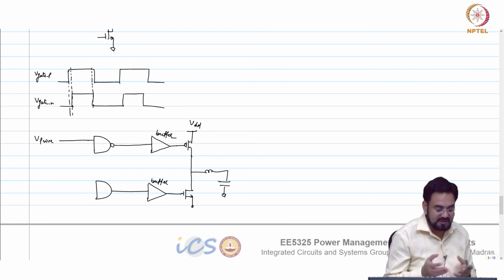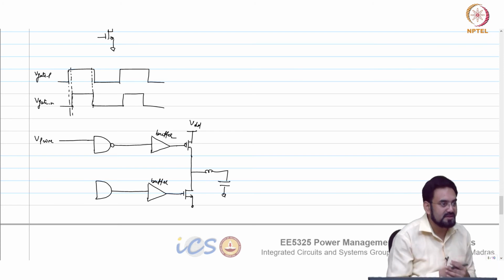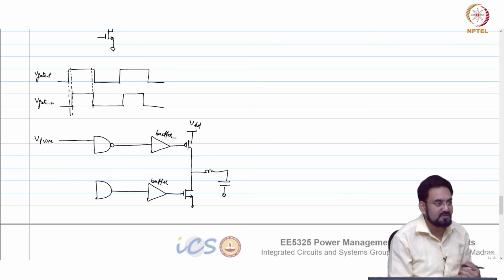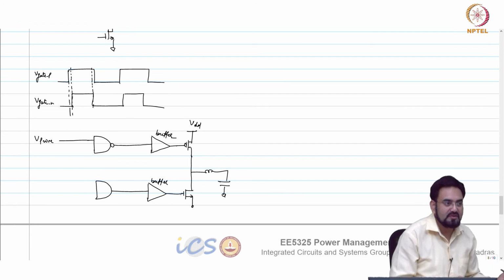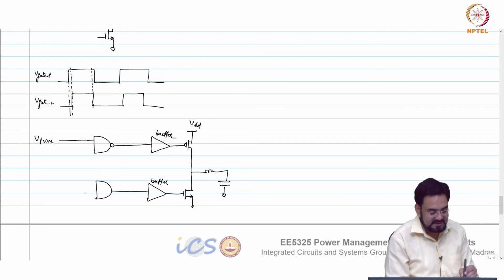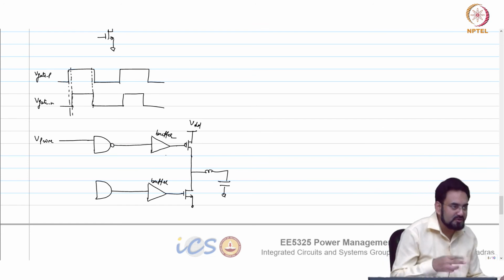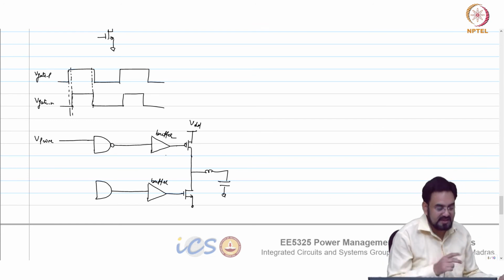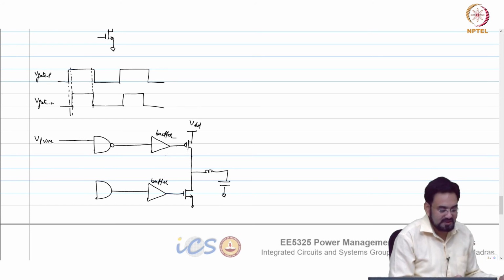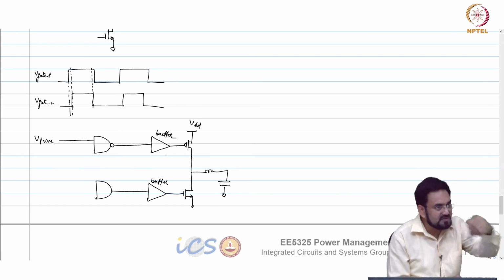You can say, okay, this can be done by using an OR gate or NOR gate, okay. NOR gate, if you make one input 1, it will go 0, but then in the logic, when you do the feedback, that may go wrong. But in this case, when the other input is, let us say, 1, then it will only depend on the second input, and that is how you build the logic actually. So that is why we are using NAND and AND gate, so that in the other case it only depends on your feedback signal.